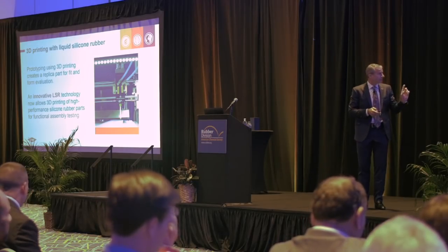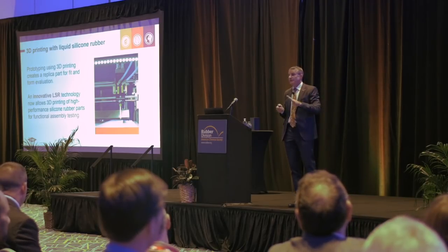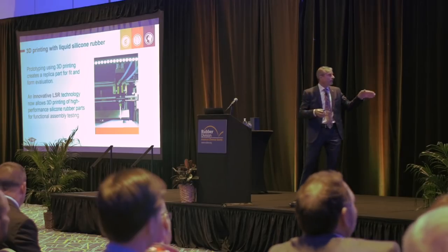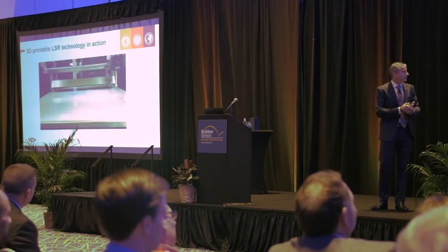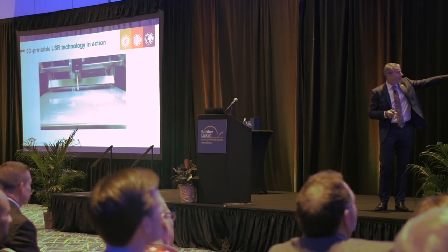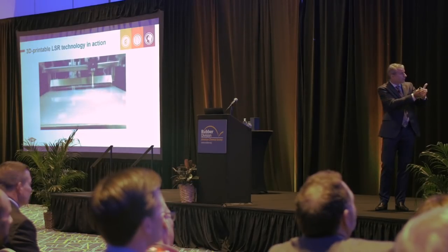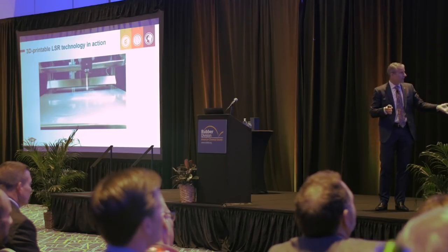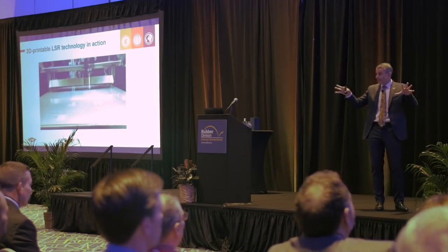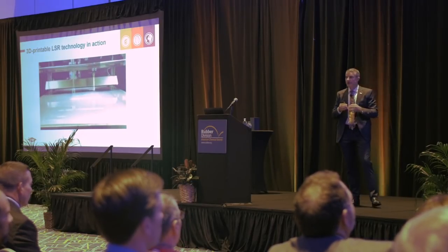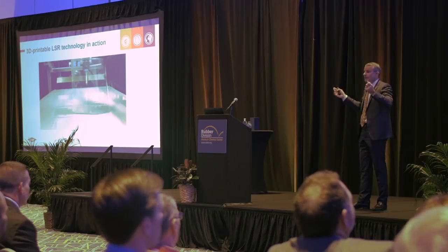You will see, I'm going to start the video. So this is the most boring part of anything. It's an ASTM slab, so there's nothing exciting about it. But it's a good way to see how this works, and you can make almost any intricate part that you would like. So you can see how the print head is now moving along, going back and forth in real time, obviously a little slower, and it builds this entire slab. Next layer comes, just goes back. And you see that IR flash cures this quickly, and it builds on it. Then you just take it off, and you have a perfectly clear printed part.